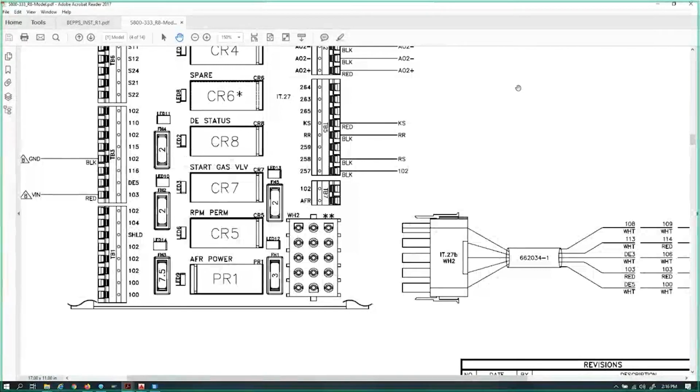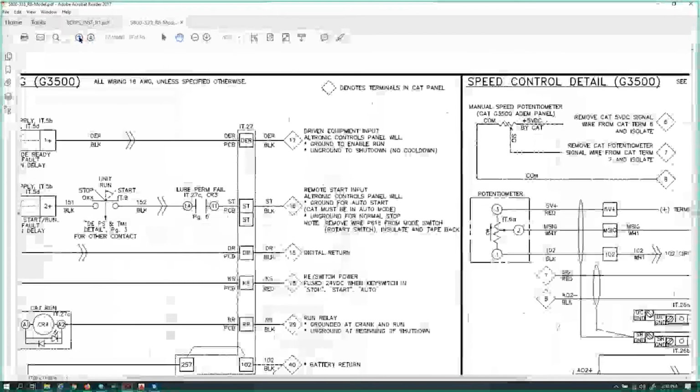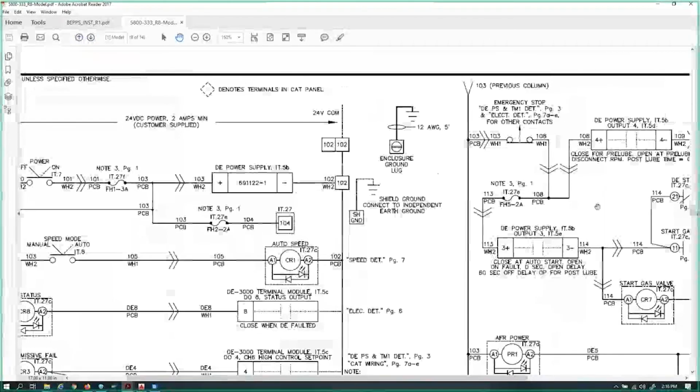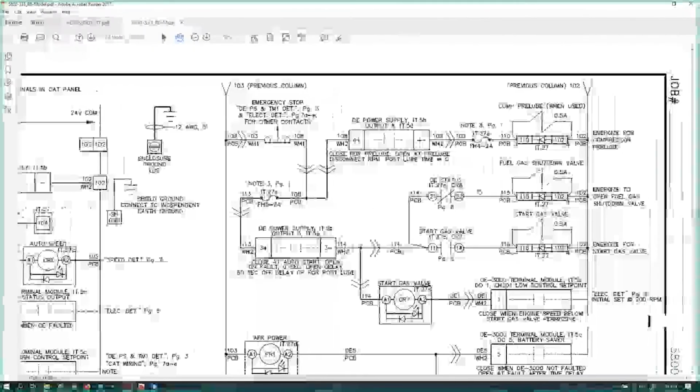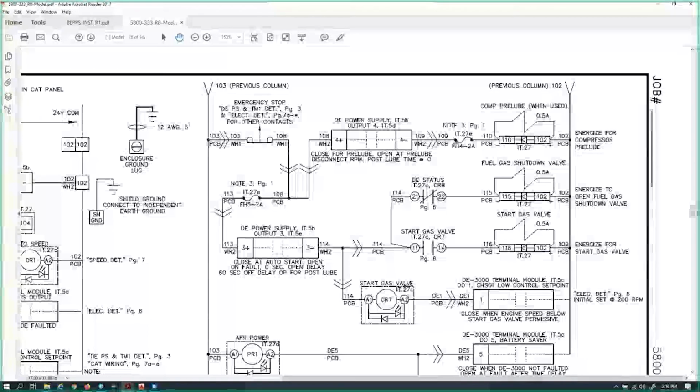Now, to explain that to you a little bit, let me jump back forward. So the first thing that has to drive that red LED on is, one, it needs to be receiving power to this end of the fuse. Second thing for that LED to light up is there has to be a load downstream. So if this was an open circuit not connected to a coil out there on the skid, he would never have seen that red LED.